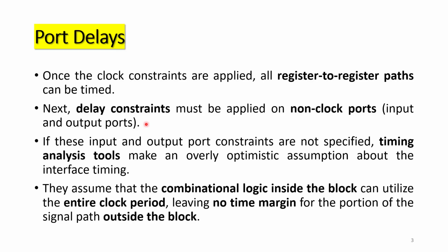As we know, there will be 4 timing paths: input to register, register to register, register to output, and input to output. If these input and output port constraints are not specified, timing analysis tools make an overly optimistic assumption about the interface timing. They assume that the combinational logic inside the block can utilize the entire clock period, leaving no time margin for the portion of the signal outside the block.